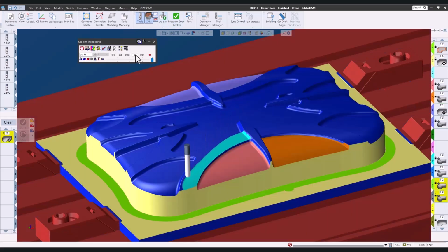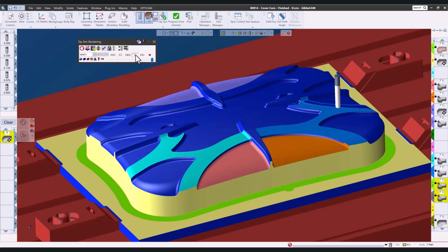Each of these toolpaths is morphing from the long side to the short side, the geodesic toolpaths in the front and the surface-based toolpaths in the back. The geodesic patterns do make a cut to the outside of the short side before finishing so that the tool is climb milling at that edge rather than pushing the chip or burr to the outside. And in the back, you see that functionally a very similar toolpath is produced by the calculations based on surfaces morphed between two curves pattern.